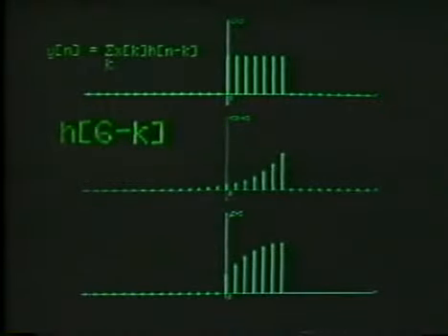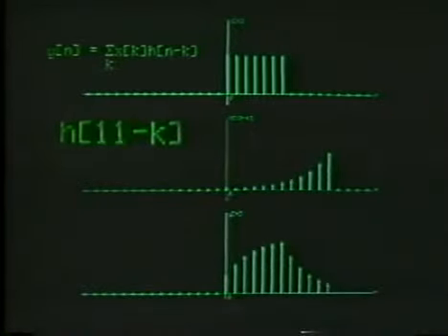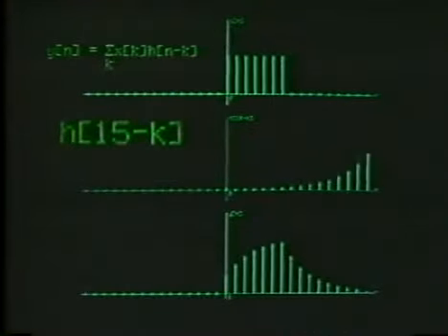until the impulse response reaches a point where, as we slide further, we slide outside the interval where the rectangle is non-zero. So when we slide 1 point further from what's shown here, the output will now decay, corresponding to the fact that the impulse response is sliding outside the interval in which the input is non-zero. And so on the bottom trace, we now see the result of the convolution.